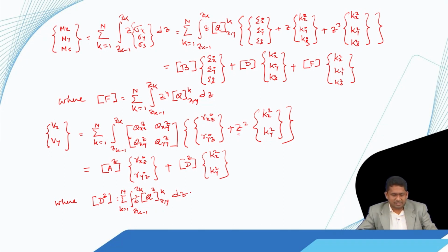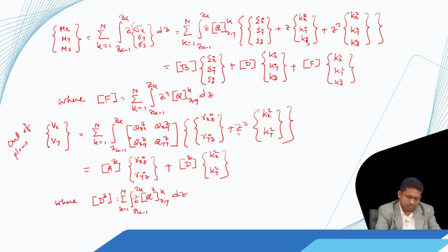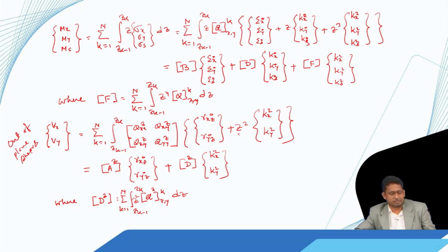So, with this the definition of the laminate stiffness is completed. So, using these laminate stiffness quantities, we can relate the stress resultants nx, ny, ns, mx, my, ms, and vx and vy, that means out of plane shears, with the displacement components, I mean the derivatives of the displacement components. Now, let us look at the governing differential equations.